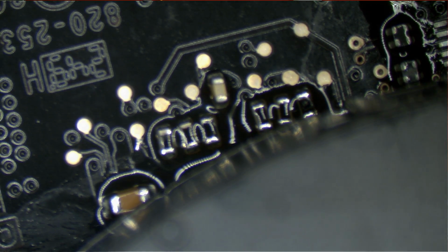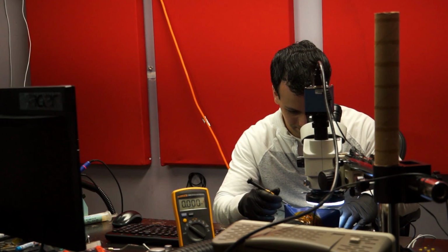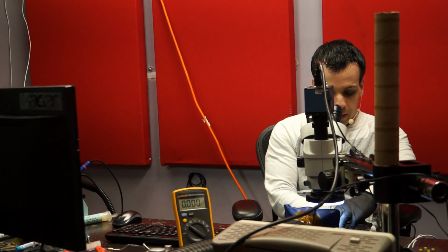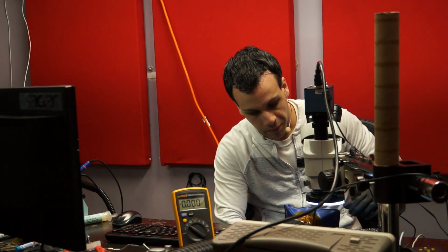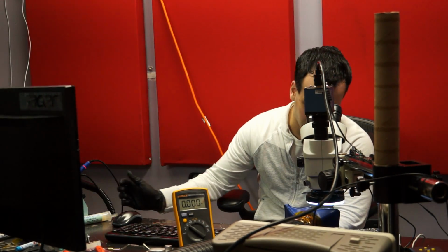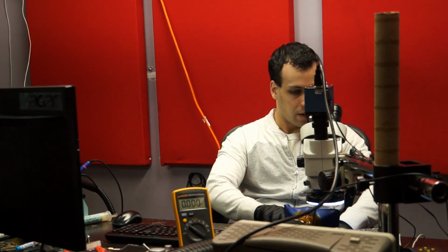Plug in the MagSafe. I plug in a fan. And I hit power. Yeah, I'm a fucking idiot. Total fucking idiot. I bridged it. But yeah, that was it. So the U7200 was the issue. It was intermittently working. I was actually getting heat in the beginning, and I'm just remembering it now. I should have noticed that immediately, but I noticed it 40 minutes in because I have no brain anymore.